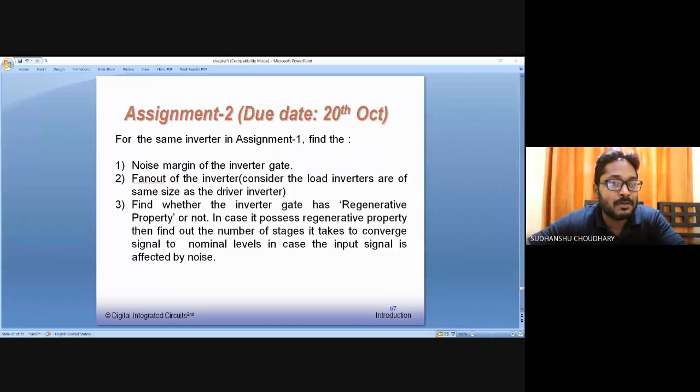You can also have a schematic of the CMOS inverter and then extract this code, and then change these values. You can change the width and length of the MOSFET, whatever transient input pulse you want to use, and the output capacitance. All these values you can edit here in this text file, and then run simulations.